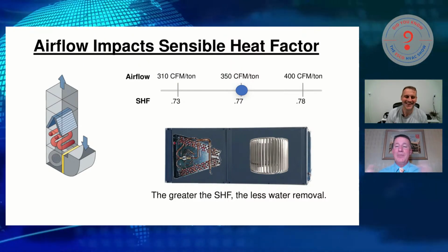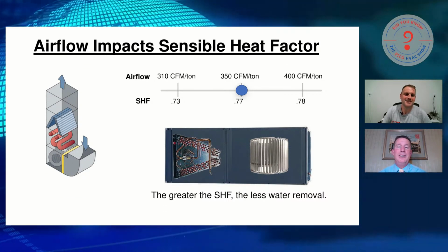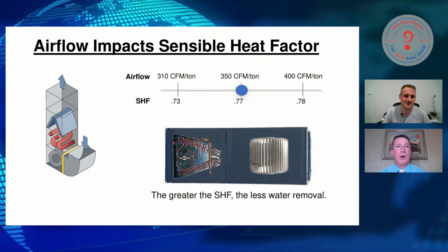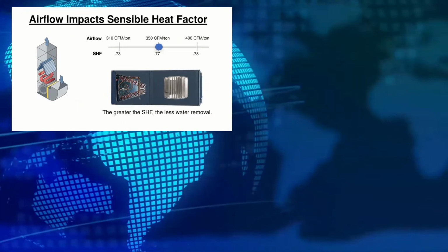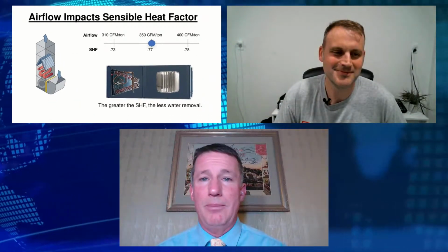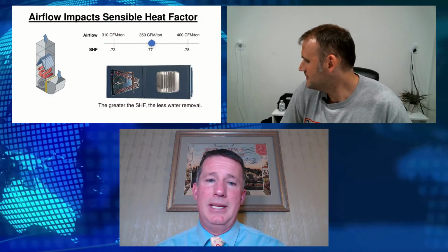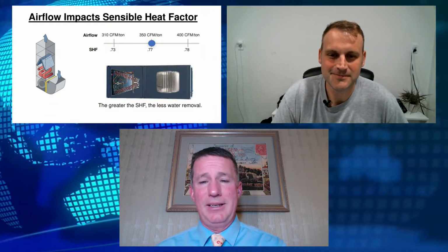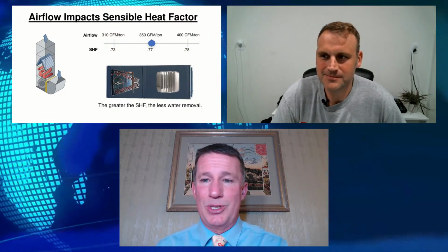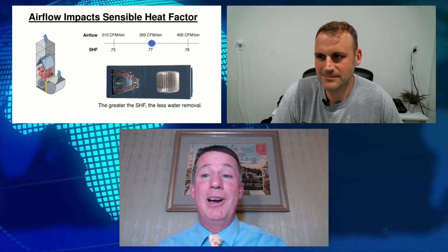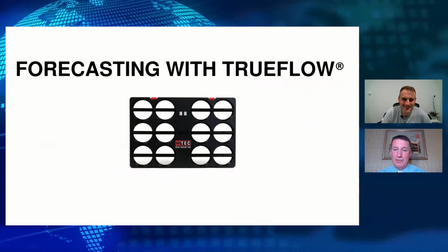When I was on the tech service side, I spent quite a few years doing dealer onboarding and site visits for tech support. When we start talking about new equipment, particularly modulating equipment like inverters, a lot of people don't understand the impact of static pressure, let alone on ECM motors. Now we're getting into variable capacity compressors and thermostatic expansion valve operation.